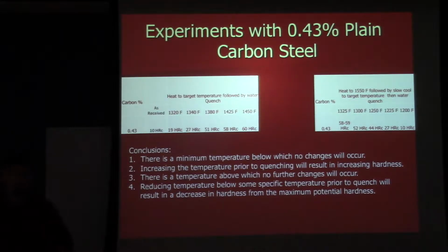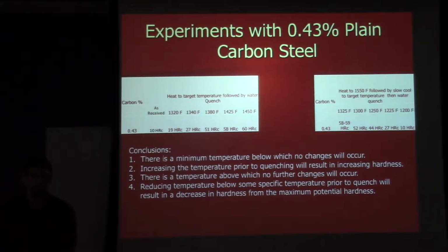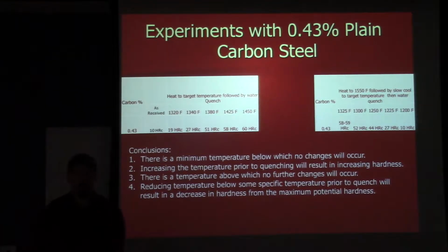One other point on that is that the hardness of pearlite is also determined not only by the fact that it's there or not, but how far apart the little plates are. The finer they are, the harder that composite acts. You can actually make pearlite very hard if you process it correctly. Railroad rails are about a 1080 in terms of composition, and they have a hardness slightly over 400 Brinell, which is roughly 40-ish Rockwell C.